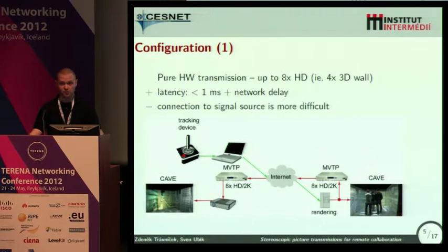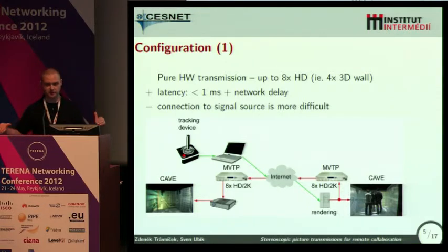There are basically two configurations we use to accomplish this task. The first one is based on MVTP4K, which is a hardware platform developed at CESNET, which has a very low latency for processing of the signal. It should add less than 1 millisecond of latency for the processing of both sides together. And it does not depend on the resolution or anything. It's just really streaming the data, doesn't care what the data is, and has very low latency.